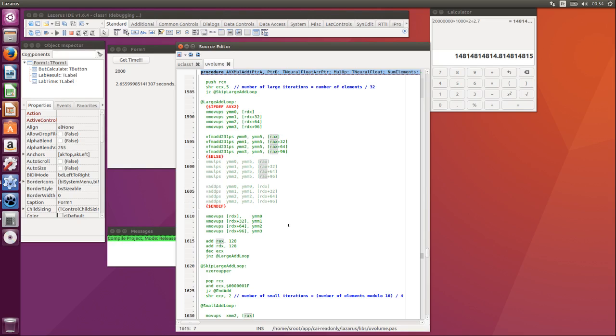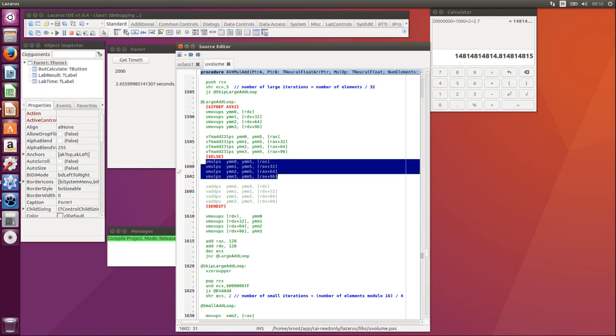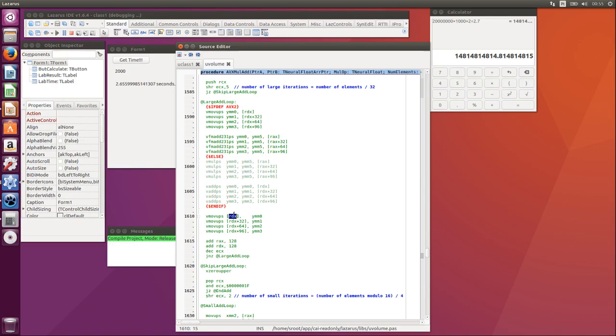So the instruction is multiply and add. Here we have the load from memory. This instruction here does both things, does the multiplication and adds the value. Or if that's not enabled, the code is very clear. Here I have the multiplication and here I add. And that's the end, and I store back to the memory.